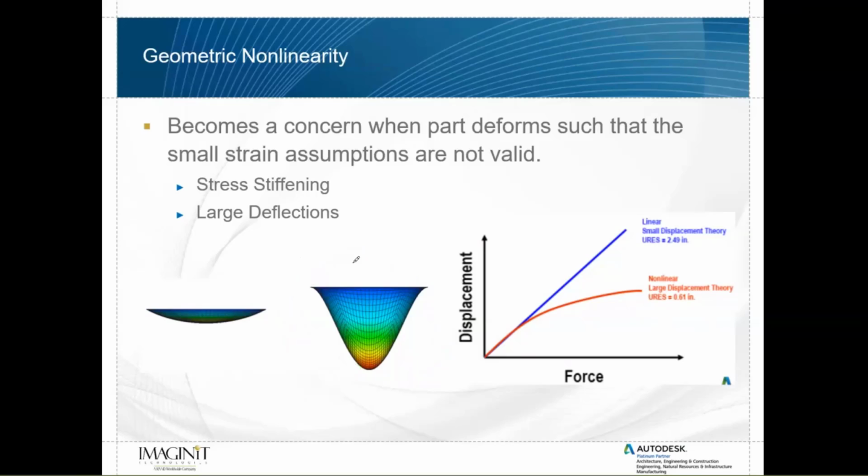But with nonlinear statics, what happens is you get a result that looks more like this, because the elements around the edge of this membrane, at the very beginning of the analysis, if you were to look at one of those elements, let's say this is the edge of the membrane and you're loading it at the beginning of the analysis sort of in the vertical direction. So you're loading it such that you're sort of bending those elements.